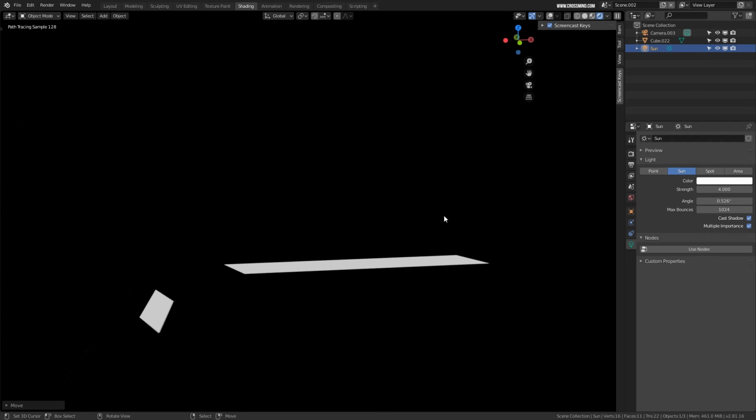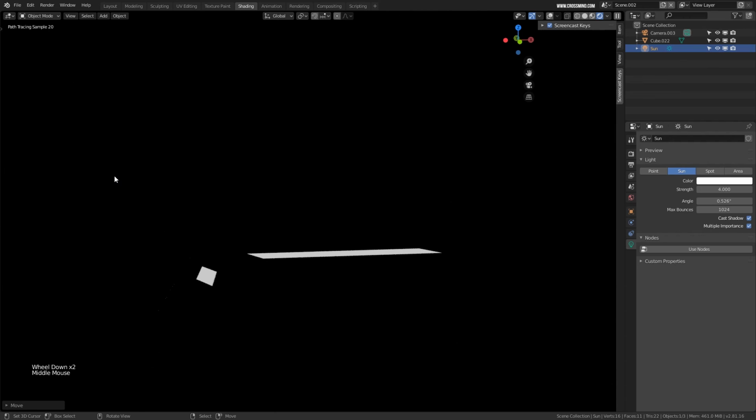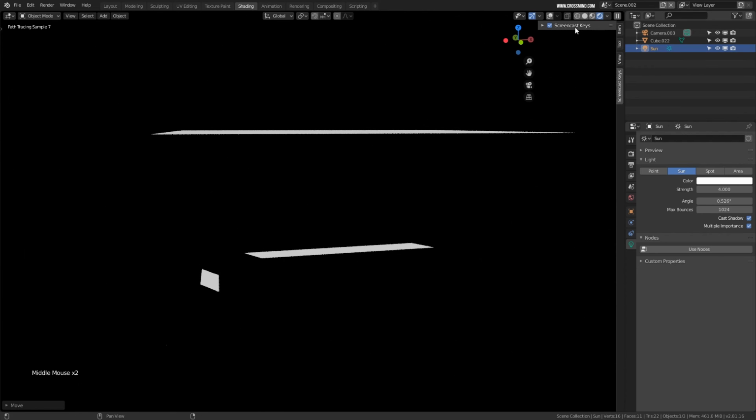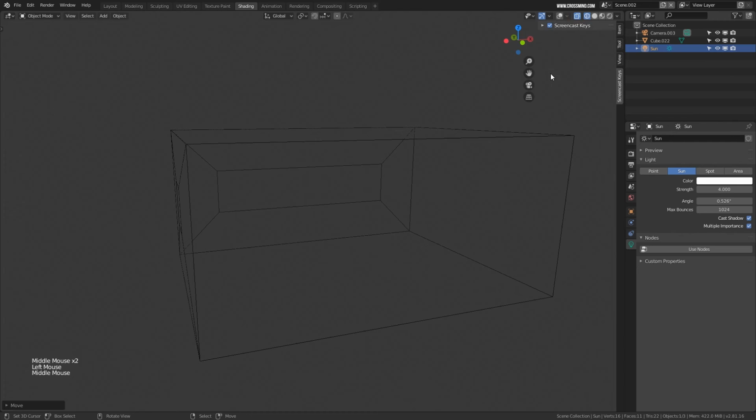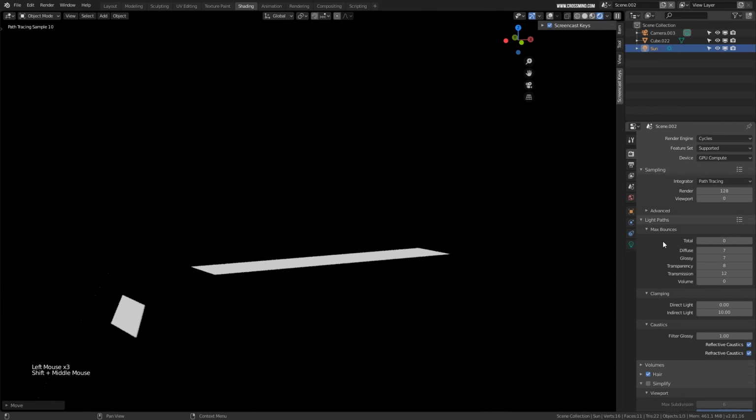That is because the global illumination is missing at the moment. We were talking about direct and indirect lights, so this example is direct light. The light is falling on this surface, and that is what you're seeing, only the direct interaction with the surface. Now see what happens when I enable indirect lights.